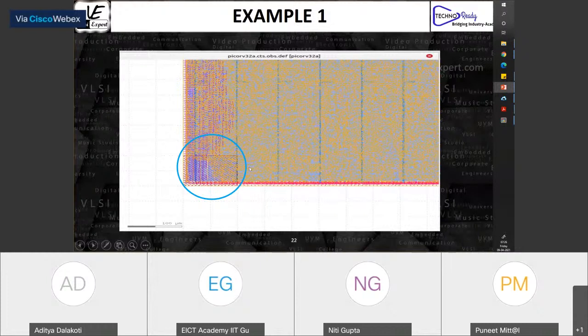You can mark regions in your design where you want lesser routing density. These might be regions right next to your macros, for example, on the boundaries of your macros, because you want to restrict those layers near the connection pins of the macros and mark those to have lesser routing in them. That should be one of the goals.